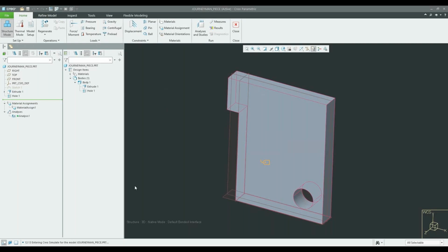So I'm just going to go back into legacy. We have steel specified. It's already in there. So if I select on this, there's the properties of steel. Now I'm going to hit cancel. Yes, I want to cancel. I can go in here and I can create a new material. This is a new solid material. Give it a name. What is this symmetry? Is it isotropic? Is it orthotropic? Is it transverse orthotropic? And you would know these things if you're creating your materials. What's this Poisson's ratio, Young's modulus?